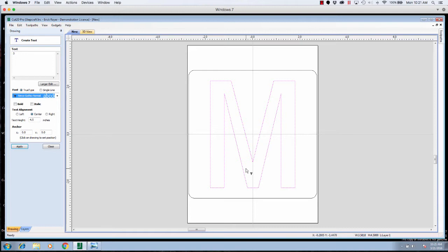So that's a problem. So what we're going to do is use a single line font, and the font I'm going to use, which closest represents, is Helvetica. It's a 1L for one line. They also have a Helvetica 3 line. We're going to use the single line. And it's included with Cut 2D. So it came with the program. I didn't have to download that extra.